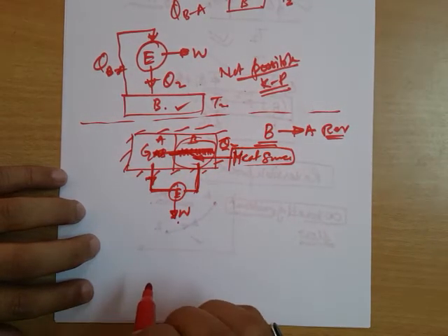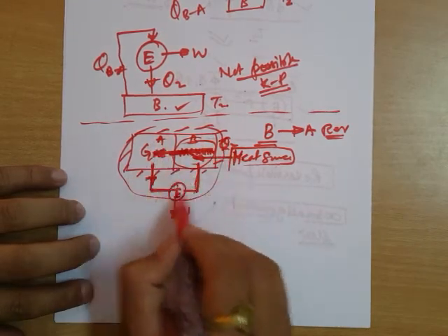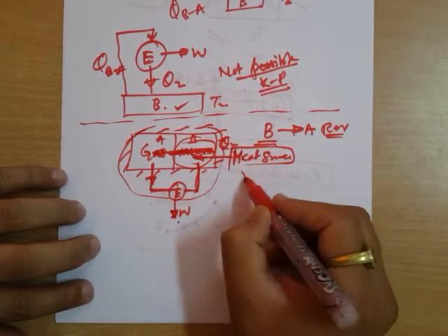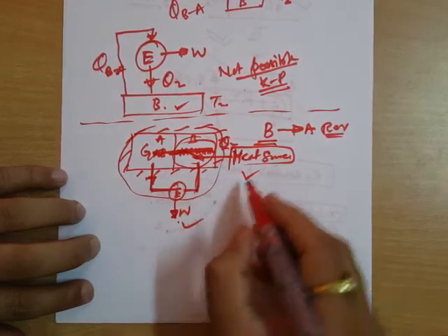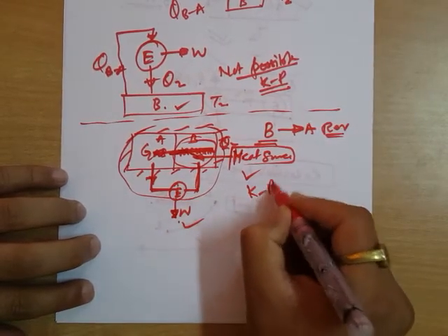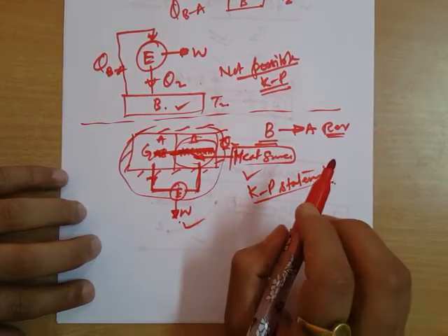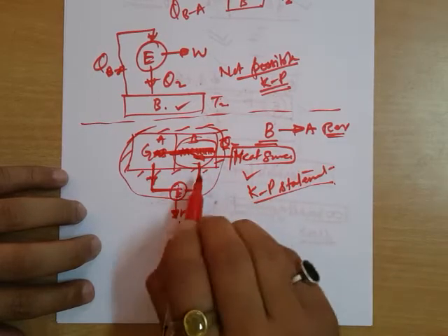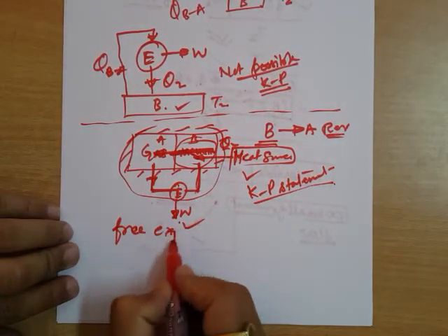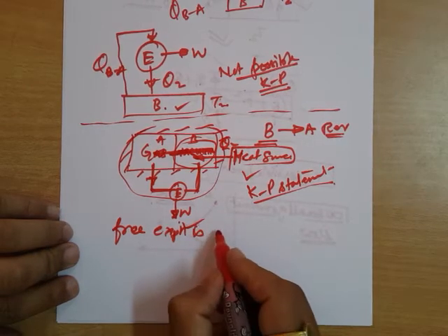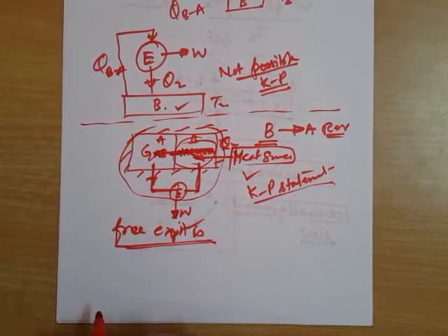So if you look at this in its totality, I am forming an engine which is working with a single energy reservoir and developing work continuously in a cycle. This is again violation of Kelvin Planck statement. Hence, this free expansion is an irreversible process, not a reversible process.